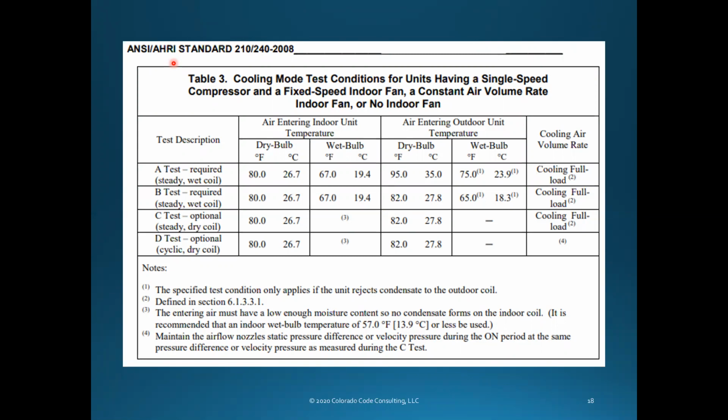They go through the same pieces. Tell me what it does, okay? The bad part about this is that the test standard doesn't match what we're trying to design to. Remember what we were designed to last week? What was our indoor dry bulb temperature we were doing for air conditioning? 75 degrees, yes? Yes, that's exactly what it was. All the tests are done at 80 degrees.